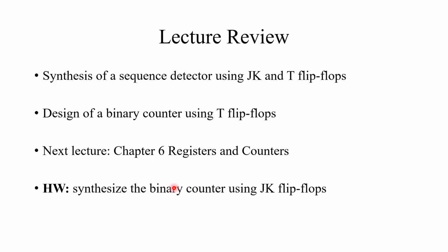In this lecture, we covered the synthesis or implementation of a sequence detector, and specifically focusing on implementation using JK and T-type flip-flops. We also covered the design of a binary counter and demonstrated its implementation using T-type flip-flops. In the next lecture, we will start chapter number 6, which is registers and counters.